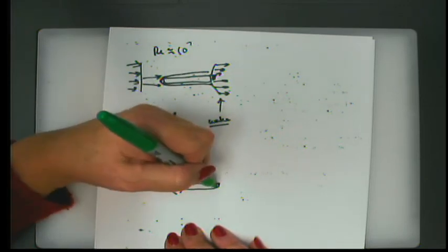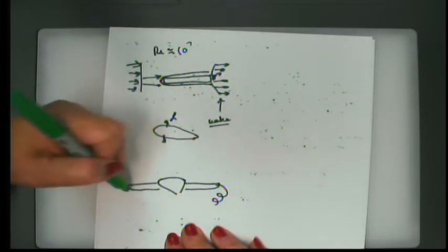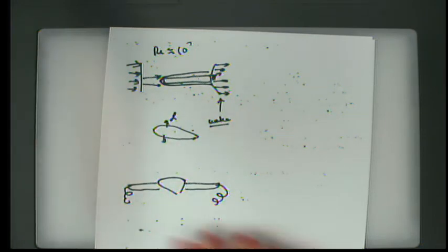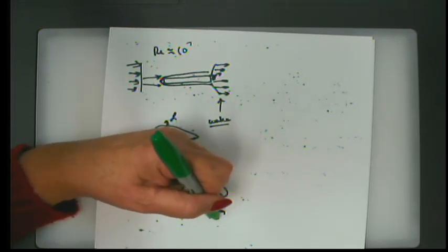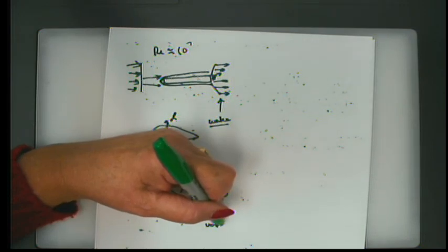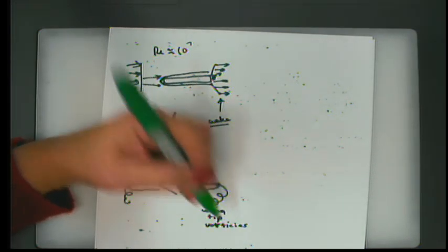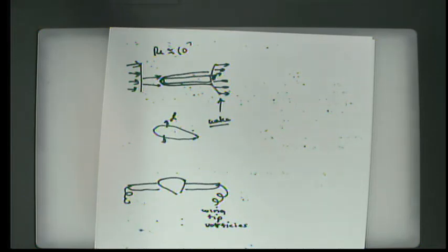And when this occurs, you'll have a wake that especially comes off on the end of the wingtip, where the wind will be really eddied up, and there will be a lot of pressure problems and pressure differentials, unpredictable pressure regimes going on in the wake of the aircraft. And those are actually referred to as wingtip vortices. And they can be very dangerous if a pilot of a small aircraft takes off immediately behind a large aircraft. So the solution for that is just to wait 10 or 15 seconds in order for those pressure differentials to dissipate.